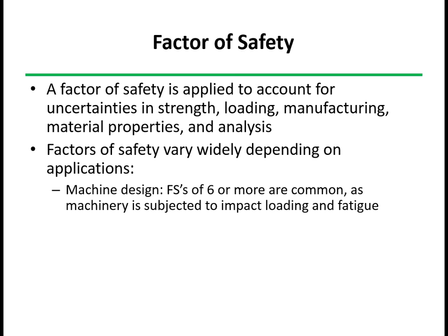In the case of machine design, where you have machinery that can be subjected to a lot of forces that are harder to analyze and harder to characterize, as well as fatigue, that is, stresses that are applied many, many times over the life, then having a factor of safety of 5 or 6 is not uncommon.